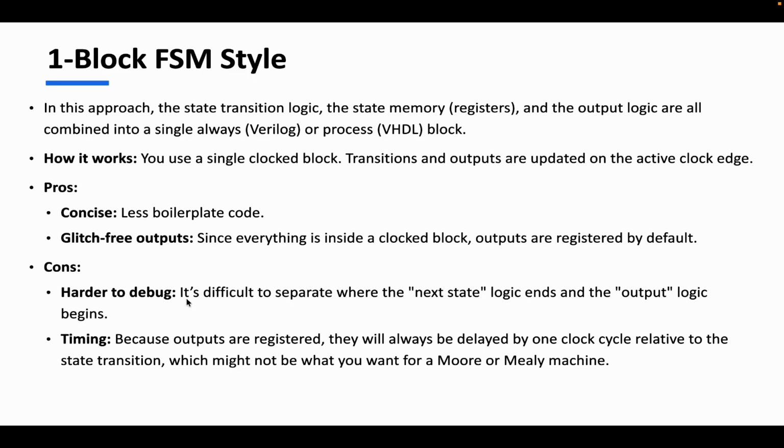It is difficult to debug, and to see where the next state logic ends and the output logic begins, since you are going to be using a lot of begin, end, and also if and always, that is a bit difficult to debug. Whereas when compared to the three block FSM style, you will have three different blocks: one for the state, one for the transition, and one for the output.